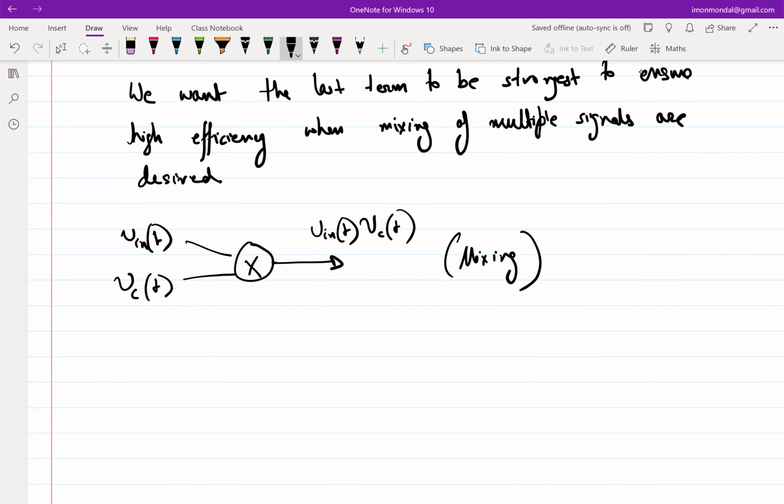So obviously the mixing operation that we saw 5 minutes back is not a very efficient one. That operation was leveraging nonlinearity, right? The next thing I would like to focus on, which I talked about in the previous lecture, is that you cannot have frequency translation in an LTI system, that is, a linear time invariant system. So we chose to break linearity, and then we saw that some sort of frequency translation is happening, but not very efficiently. So we will try to break the time invariance, and then see what happens.